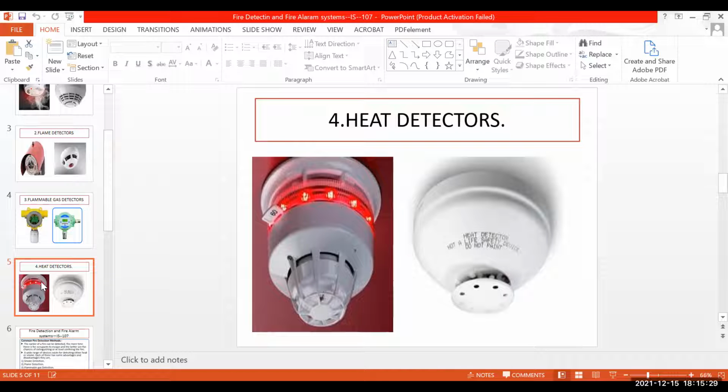While cleaning these AC filters, so much dust was there, and these maintenance people didn't protect the smoke detectors. While doing this type of maintenance, we have to cover the smoke detector with some tape so that no dust goes inside.